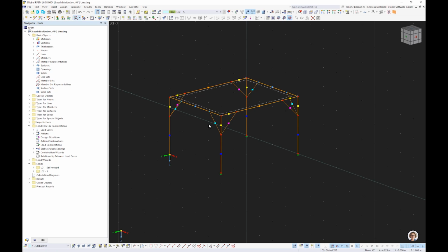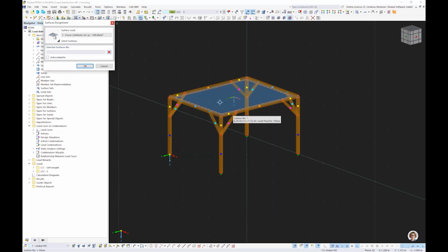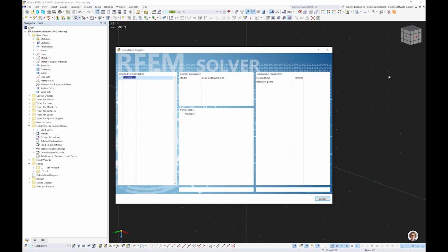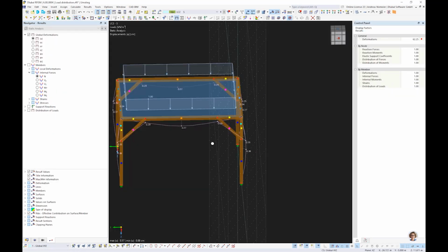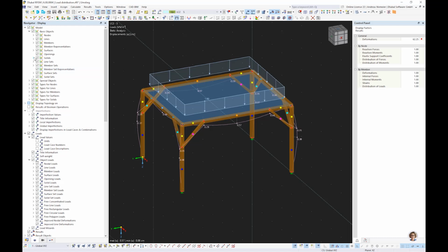And now we have the surface inside. You see it in rendering, and now of course you can apply here maybe the projected snow load in Z, standard size is 1, and apply it. And if we calculate it, we get, let's say, forces on the structure, although this surface has no effect. So really cool. We have no surface forces. Yeah. You can watch what happens inside. Yeah. You can say surfaces.